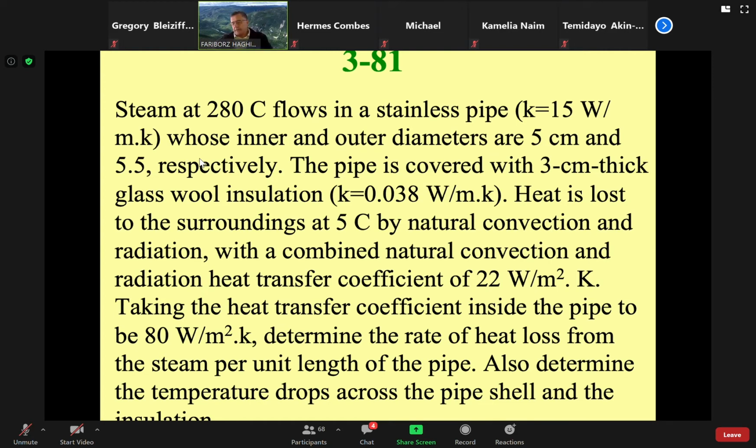Therefore, you have all the information. The best thing is to first draw the thermal network of the problem. You have 4 sections. Inside, you have resistance to the convective heat transfer inside the pipe. You have conduction through the wall, then conduction through the insulation, and from insulation to outside. Therefore you have 4 resistances. For outside and inside the pipe, we can clearly define the resistances as 1/(2 pi R L H1) and 1/(2 pi R L H2).